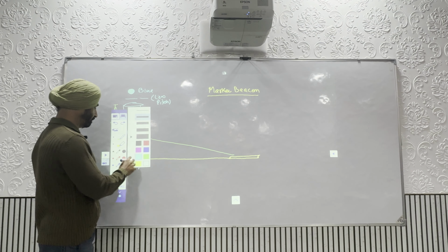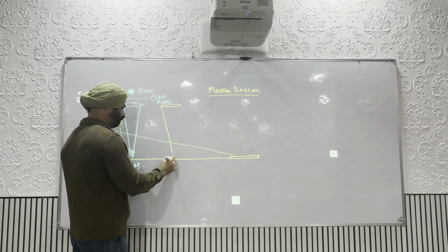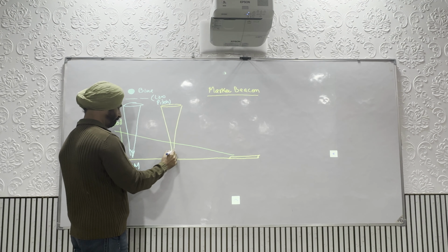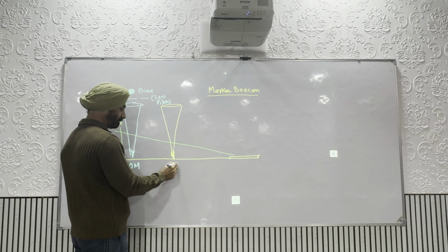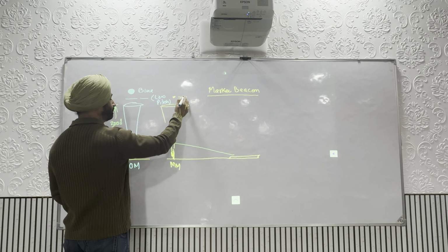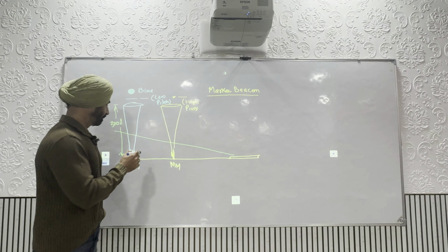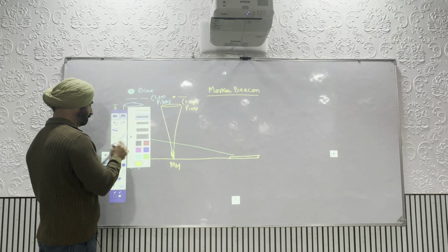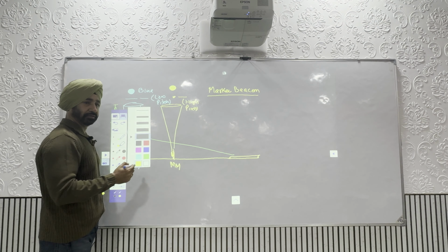Similarly, as you come closer, you have the middle marker, amber color. Amber is more of orange. When you are over this, you hear dot dash in high pitch, and you will have the amber light in the cockpit.